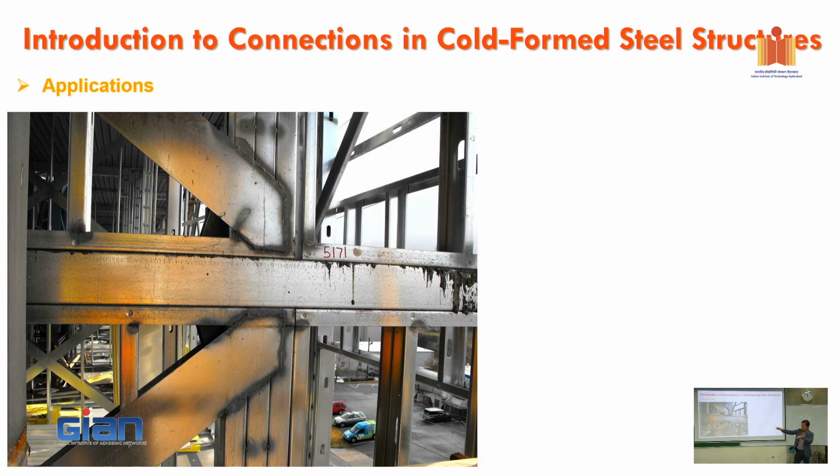Importantly, you have a big load and you divide it by the number of screws, and you get the single capacity of one screw. And for that one screw you can compare the different failure modes, all right? Tilting, bearing, shear, whatever, and you have to check it. The smallest one is the one that governs your design. Then if your connection needs 10 or 20, you just multiply by the number of screws. Do I answer your question?